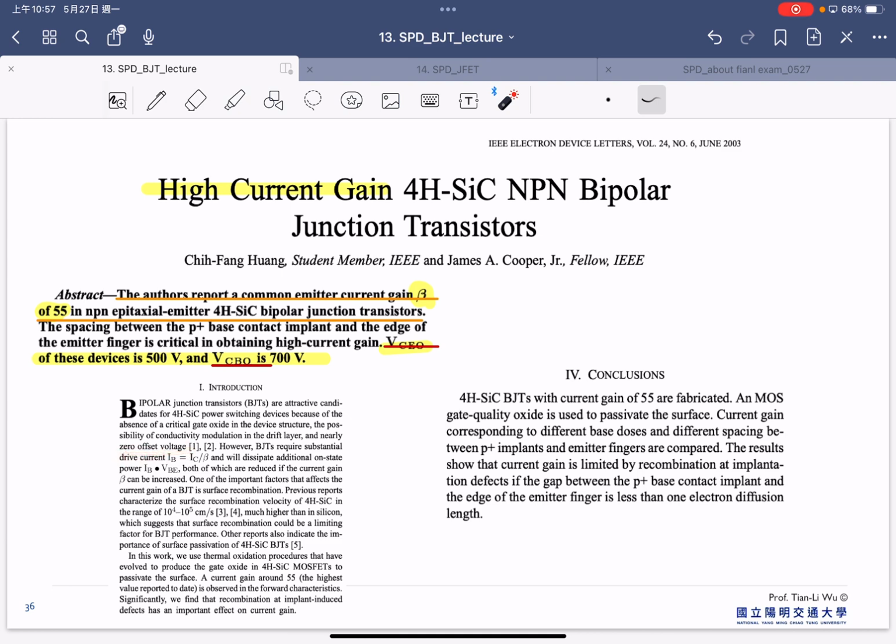So these are some background information on why people still feel very interested in the BJT, because first of all they don't have the oxide, and the oxide is one of the issues for reliability. So ideally, if the device doesn't have oxide, it should be a very interesting, stable and reliable device. And of course, what we are interested in is always what comes after the however.